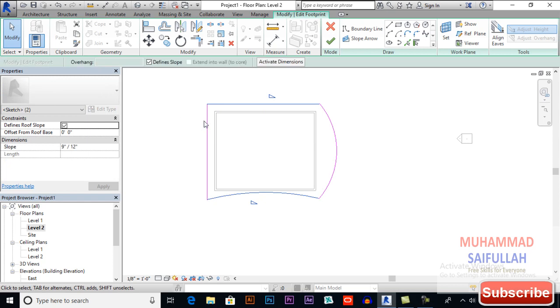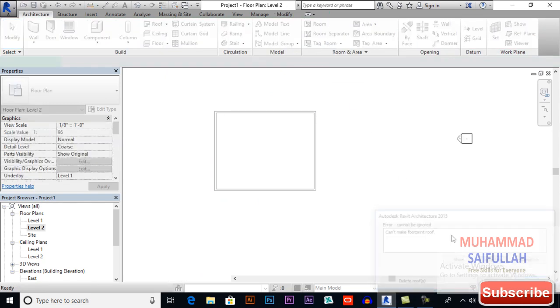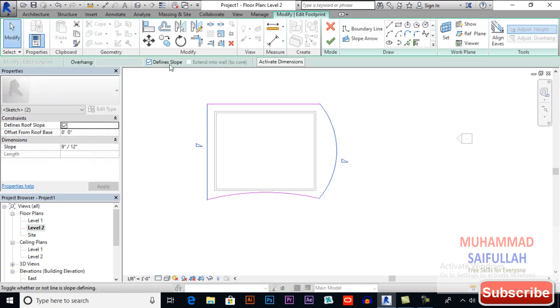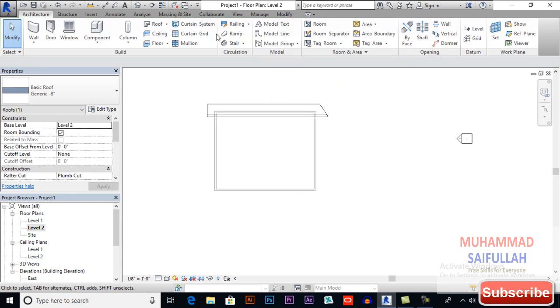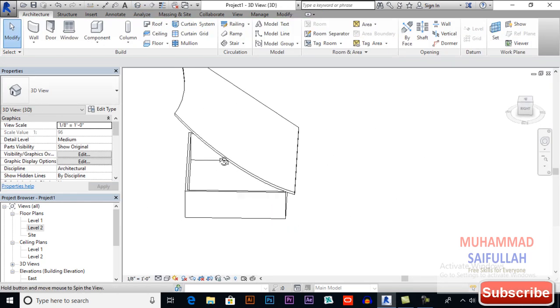Sorry, select again and define slopes. Try this one. You also can't do it. So this shape is not eligible for defining slopes. You can define one side of your roof. So finish edit mode, and now switch to 3D view. So this is how it works.